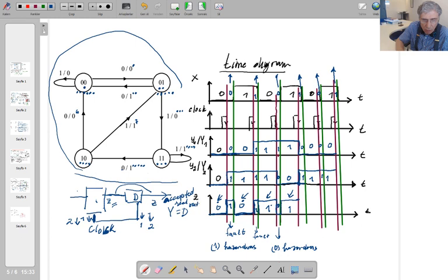I mean no false outputs, no faulty outputs, hazardous or not, are seen here, because I am transferring the Z information just before the clock pulse to here. So that is the solution to that Mealy machine problem that we faced. That is the end of this video then.